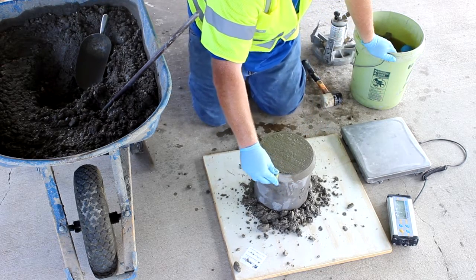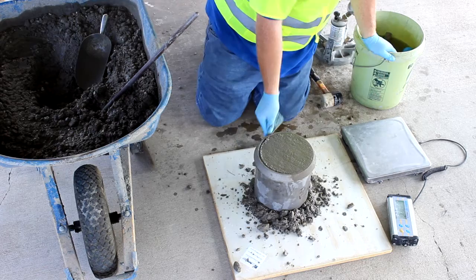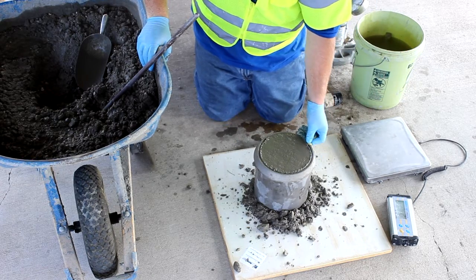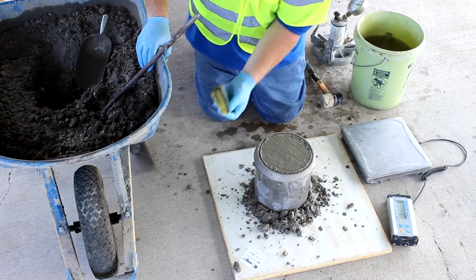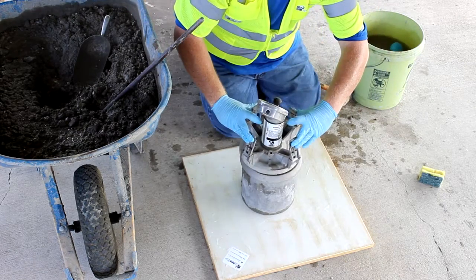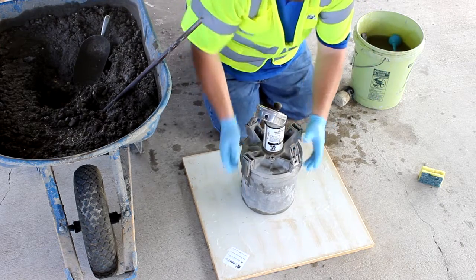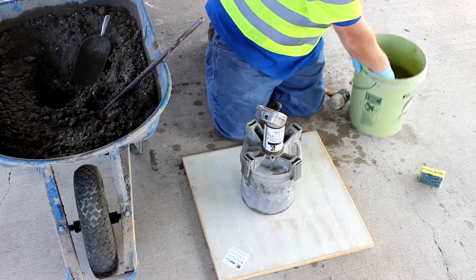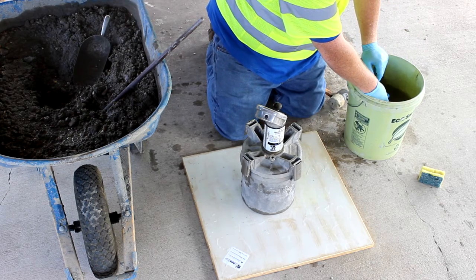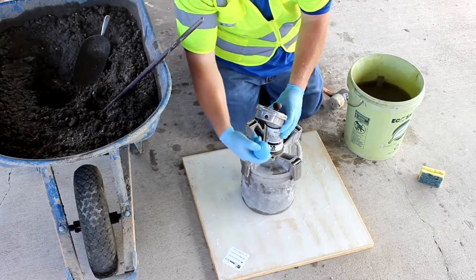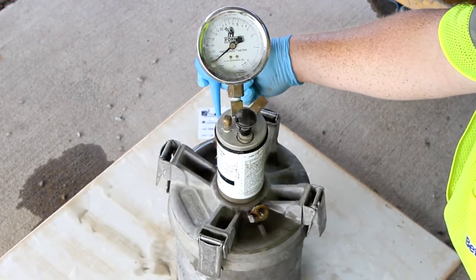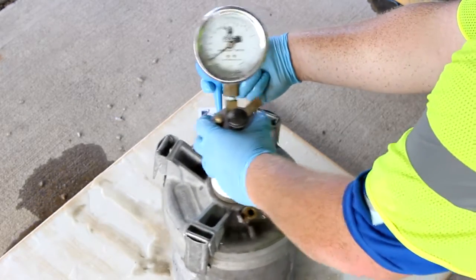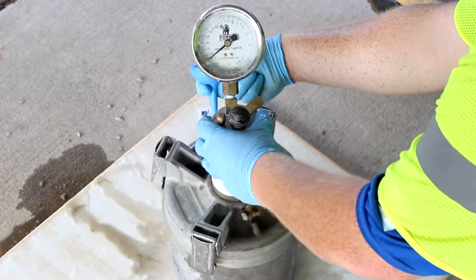Thoroughly clean the flanges or rims of the measure and the cover assembly so that when the cover is clamped in place, a pressure-tight seal will be obtained. Assemble the apparatus. Confirm that the main air valve is closed between the air chamber and the measure, and open both petcocks. Using a rubber syringe, inject water through one petcock until water emerges from the opposite petcock. Inject water until there are no longer air bubbles present. While continuing to inject water into the petcock, jar the meter gently until all air bubbles are expelled from this same petcock.